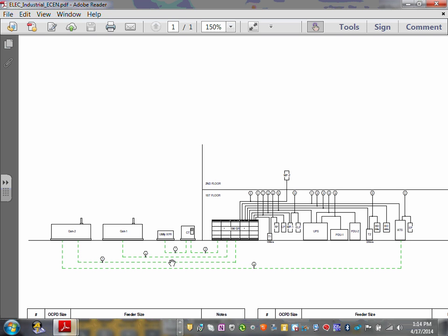In the power industry, I'm sure a lot of us are engineers here, guys. We have something called the power riser. You have to come up with the power riser. That's the big picture, I call it. It's a skeleton for the building. And you sit there and negotiate. The most important thing we decide is what type of voltage system we want to build this building at. And being an engineer, the first thing you should say is 480/277.